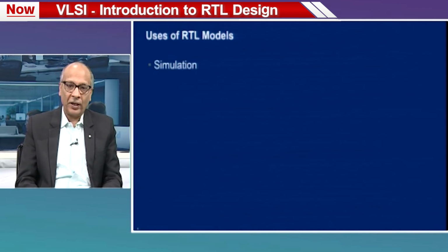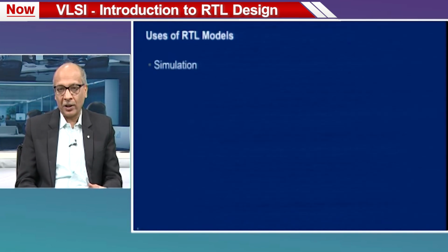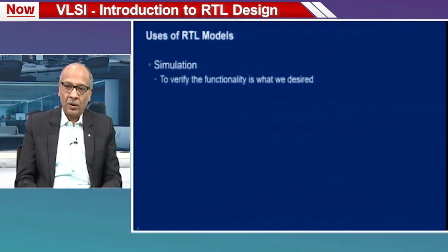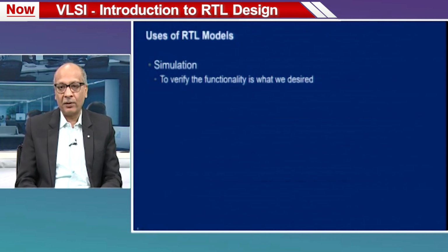So, the first use of an RTL model is to simulate. We talked a little bit earlier that we can simulate all kinds of circuits, all kinds of modeling abstraction. So, why do you want to simulate? To verify that I have achieved the functionality that we desire. I have certain functionality in mind, I wrote the description of that functionality in the form of RTL. I have to simulate it to make sure that the functionality is achieved. It is not giving an incorrect functionality.